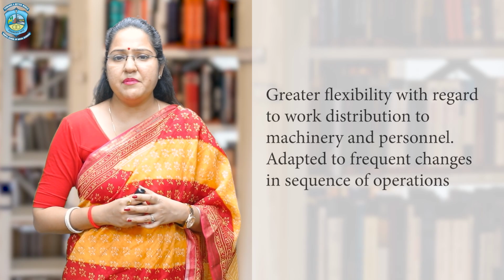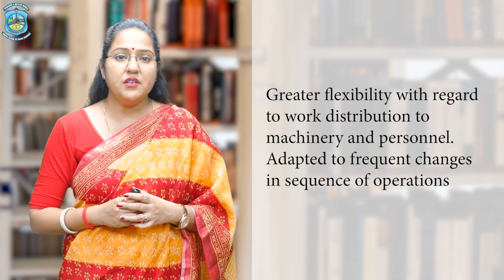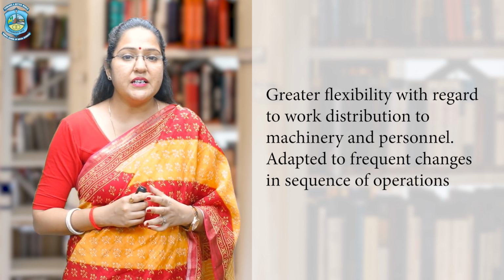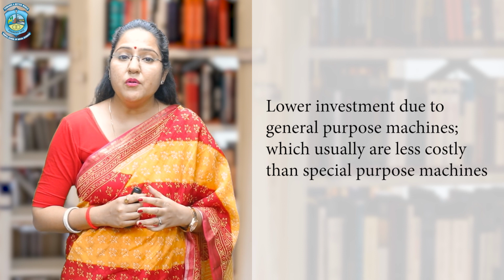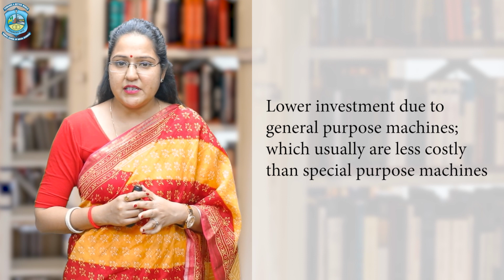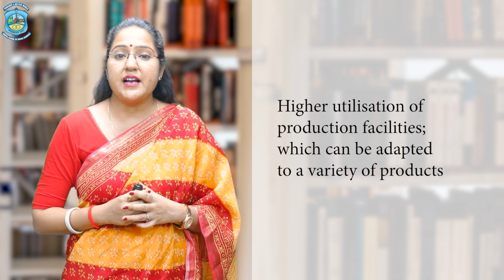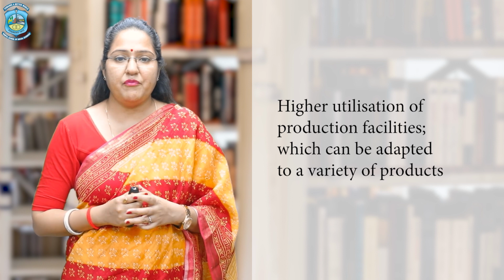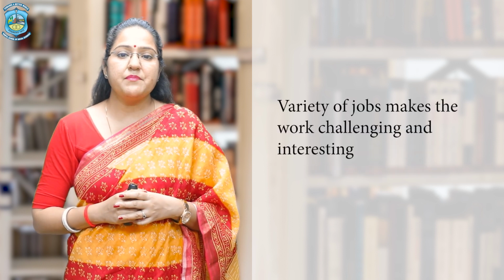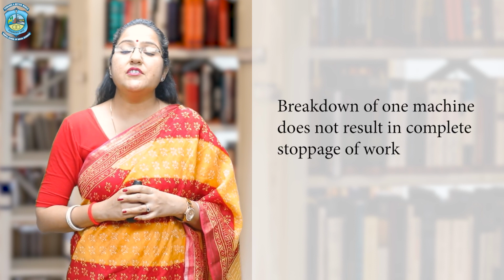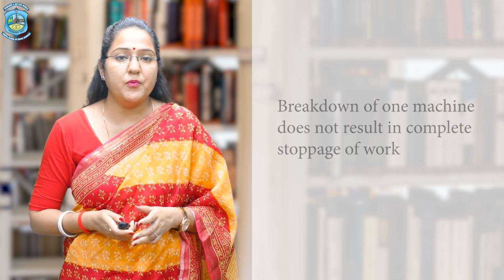It gives greater flexibility with regard to work distribution, to machinery and personnel, adapted to frequent changes in sequence of operations. It lowers investment due to general purpose machines, which usually are less costly than special purpose machines. Because of this, there is a higher utilization of production facilities which can be adapted to a variety of products. A variety of jobs makes the work challenging and interesting. Breakdown of one machine does not result in the complete stoppage of work.